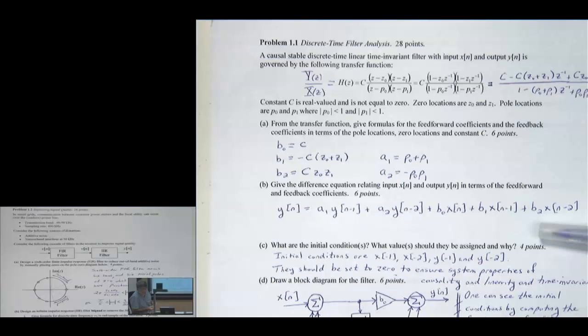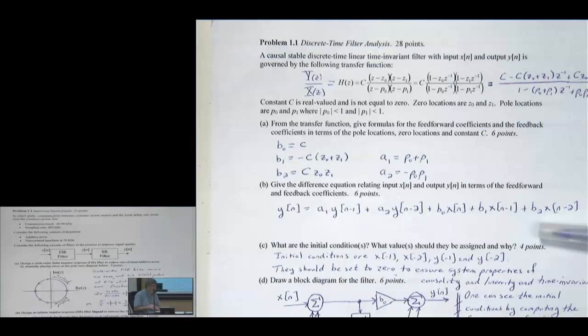Sampling rate is 400 kilohertz. This is a real system. And I asked you to consider the following sources of distortion: additive noise and a narrowband interference. This is right out of question 3.1 in homework. And we talked about these things in lecture too. So I'm going to give you a cascade of 2 filters. The first filter is going to be the bandpass filter to attenuate out-of-band additive noise. And then we'll try to cancel the narrowband interferer with a notch filter.